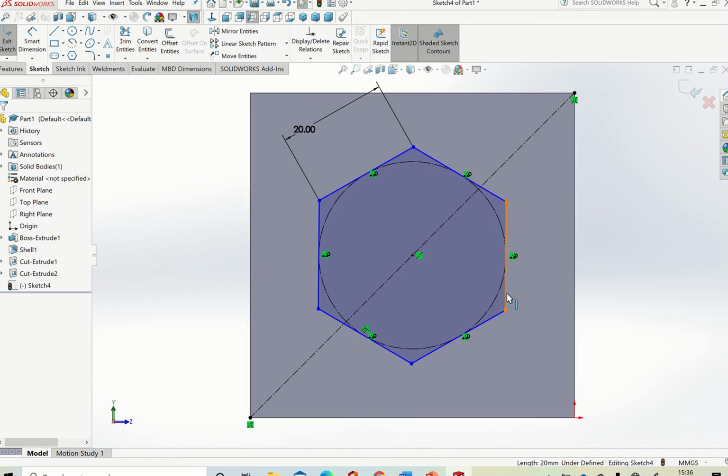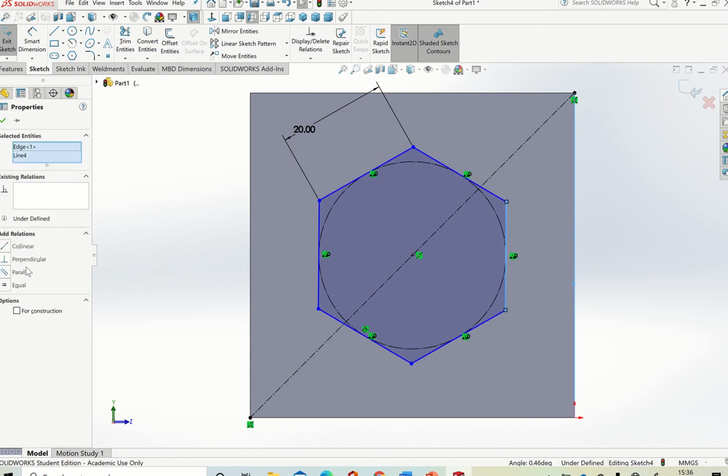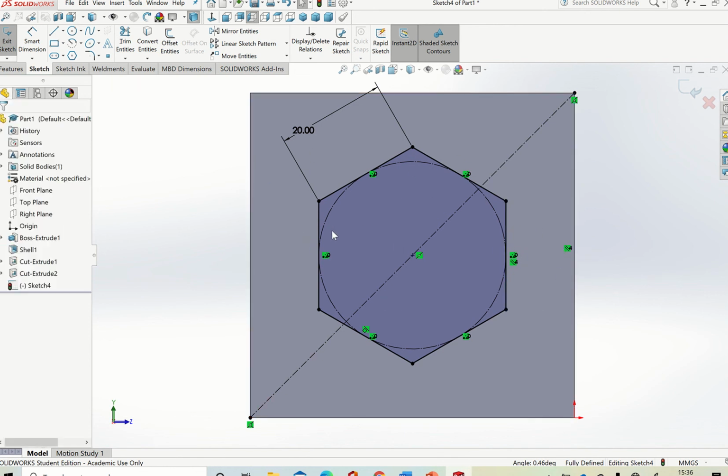And what we can do here is just make this line, highlight it. Okay, that's parallel, so I just made those two lines parallel, so therefore everything is straight and fixed, and now we can see that because my polygon has become black, just identifying that it's defined.